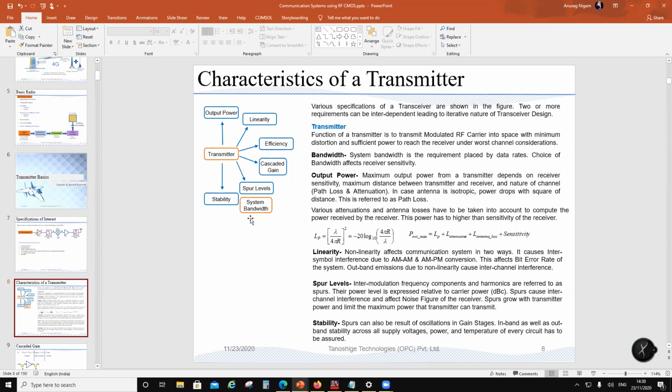Okay, so what is expected from a transmitter? You will put out a certain power. And how do you decide the power? It is not just with the transmitter that you decide the power. There is a receiver also, which plays a role. So basically, if you start with a certain size of a cell, then you should look at what peak power a transmitter should be capable of.